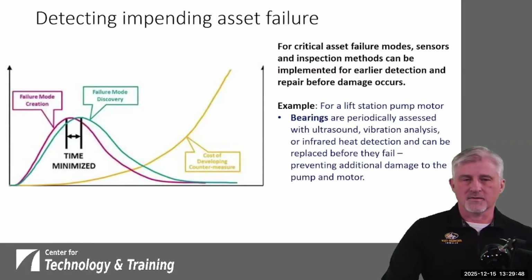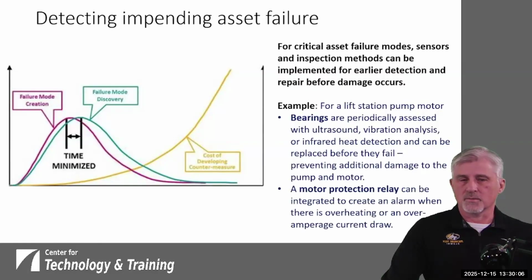So let's look at a lift station pump motor. The bearings are periodically assessed with ultrasound, vibration analysis, or infrared heat detection, and can be replaced before they begin to fail, preventing additional damage to the pump and motor. A motor protection relay can be integrated to create an alarm when there is overheating or an overamperage current draw.